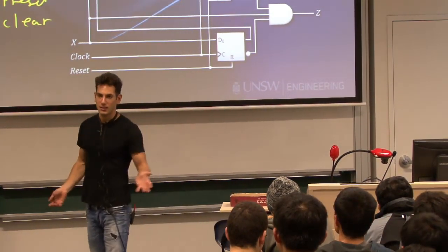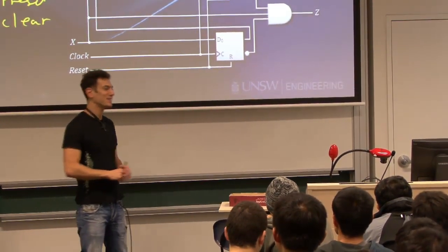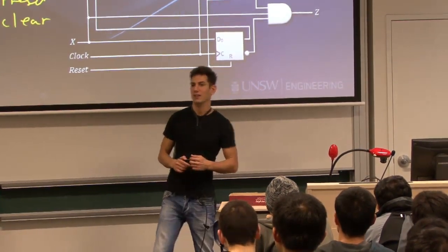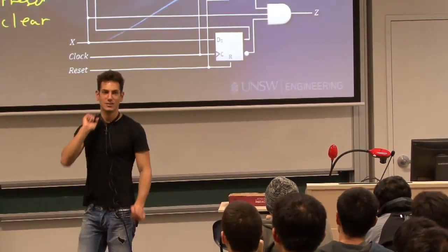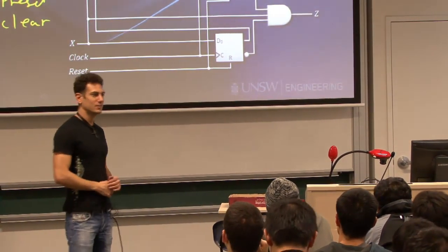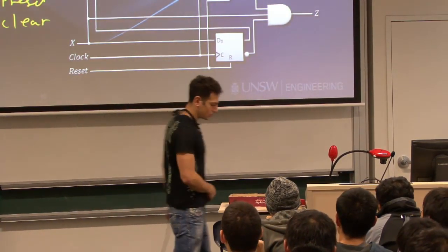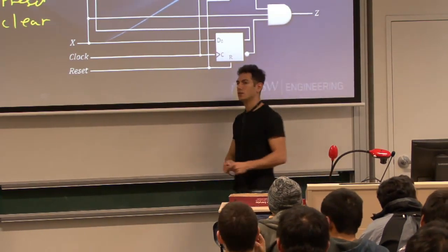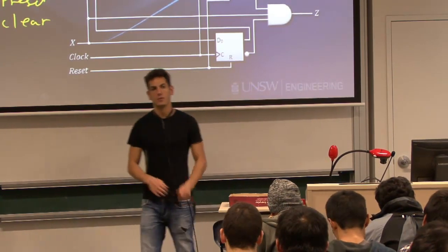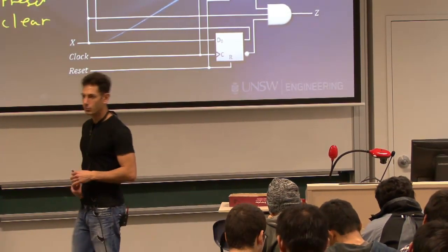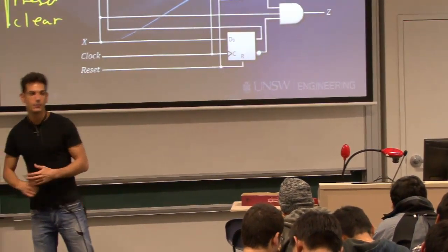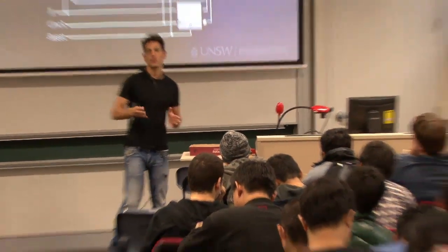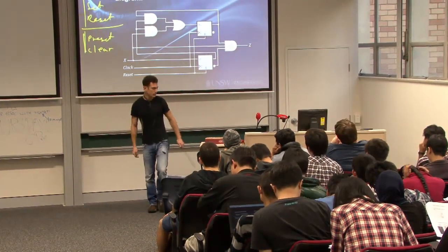First thing, don't panic. All right? A lot of people do panic when they see a state machine. They don't know where to start. Start with a circle and put an A right there. Call it your initial state. And then start to think, all right, what's going to happen for my initial state? What are the possible inputs? What do they imply towards the operation of my machine? And it really depends on what your machine needs to do.